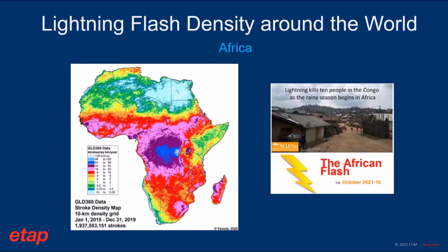Here, the stroke density map that is provided could be based on different factors. Some of them may be related to lightning directly hitting the structure before it hits the ground, or sometimes going directly from the sky to the ground itself. In either case, the evaluation of the lightning flash density and the corresponding area around that particular affected structure is important.